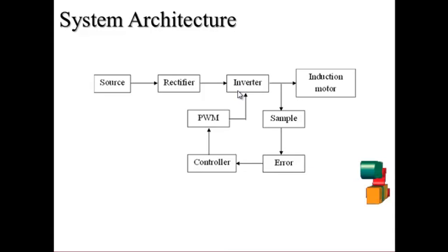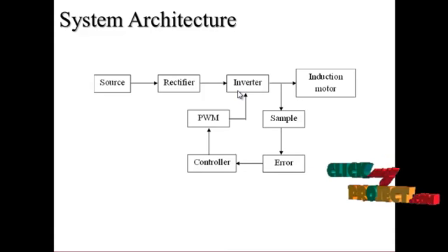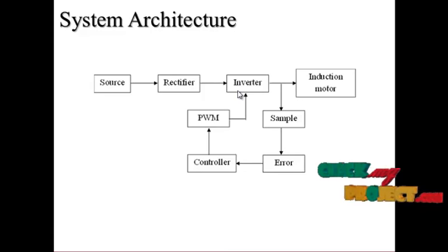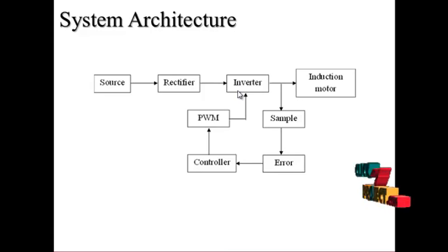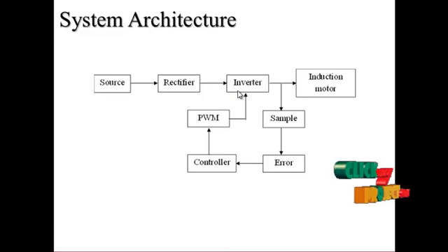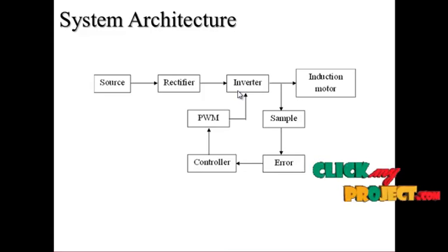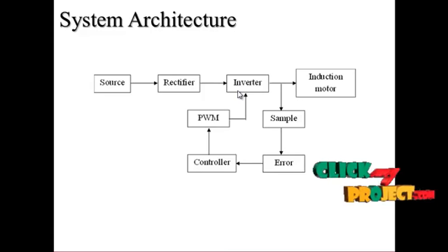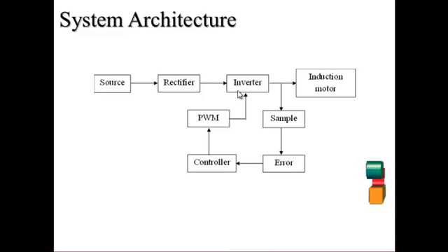The samples will be used to get the frequency of the induction motor, and that frequency will be controlled by PWM, generating the switching pulses. The switching pulses will control the inverter using AC pulses with the specific frequency of the reference torque, and they will control the induction motor torque as user defined, which helps industrial applications get better results.